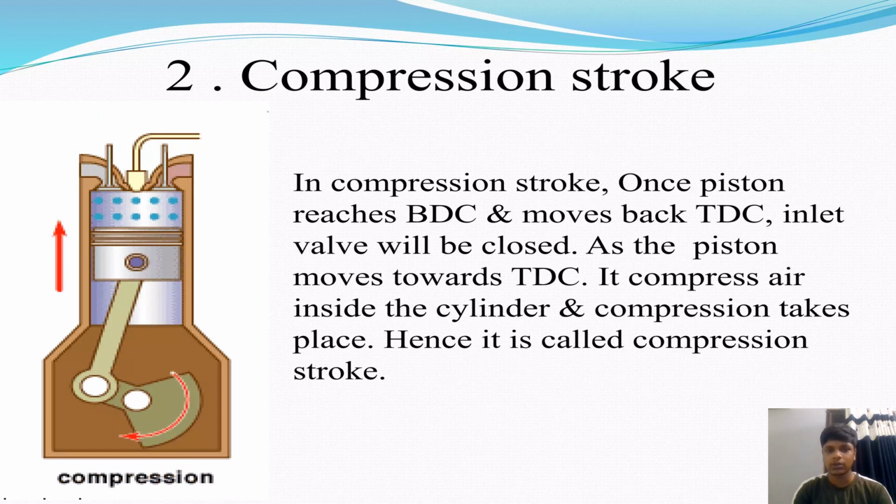Next, compression stroke. In compression stroke, once piston reaches BDC and moves back to TDC, inlet valve will be closed. As the piston moves towards TDC, it compresses air inside the cylinder and compression takes place, hence it is called compression stroke.